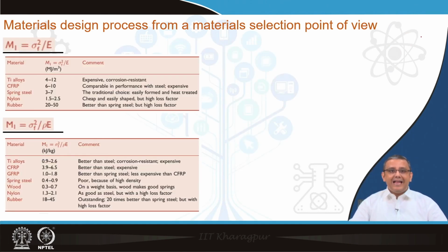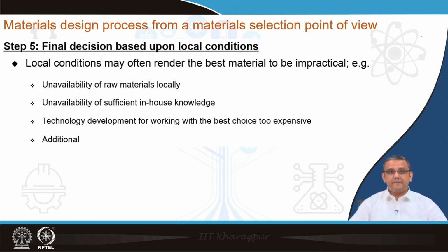And again for rubber, you might think that rubber is an ideal spring, but you have to keep in mind that rubber has a very high loss coefficient, and also rubber is pretty bad for high temperature applications. So, all those parameters you have to keep in mind, and when you design your new hybrid materials, your hybrid material design will actually have to follow these materials selection conditions.